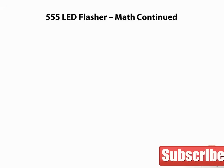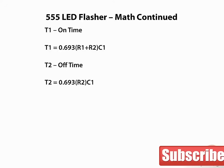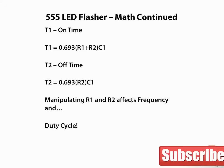For those who are interested, T1, or the on time, is given by the equation T1 equals 0.693 times (R1 plus R2) times C1. And the off time, T2, is given by the equation T2 equals 0.693 times R2 times C1 for astable operation. We can see by manipulating the values of R1 and R2, we can adjust not only the frequency of the oscillator, but also the duty cycle. Try it out and see if you can think of some neat applications for this versatile circuit.